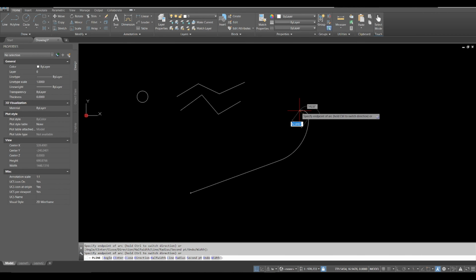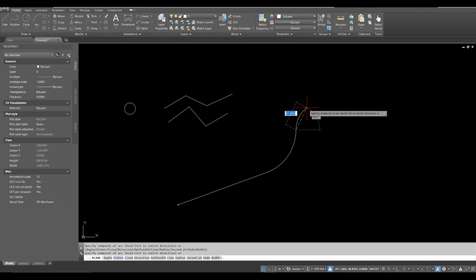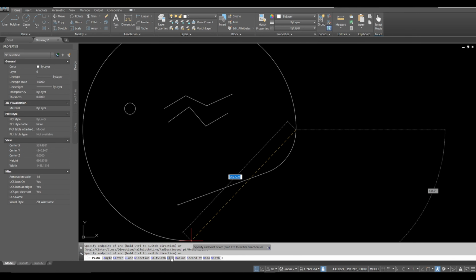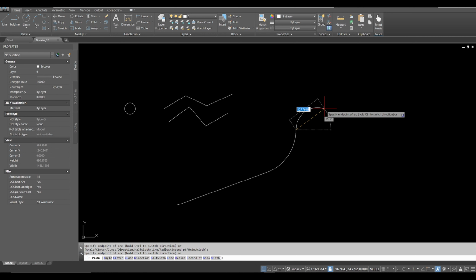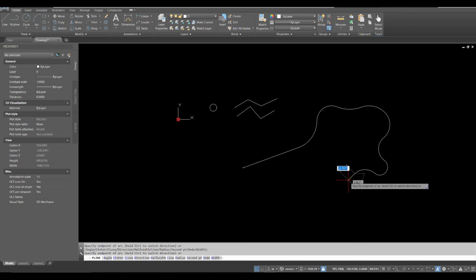Now you can see that it's already asking me to sort of create another tangent arc on top of that. So if I don't ever switch back to the line command by pressing L space inside of here, right, in our polyline subroutine, I'll keep making arcs and they'll all be tangent to the last arc that came before it. And they look cool. Now, once I do eventually reinvoke my line command, it's a little tricky.